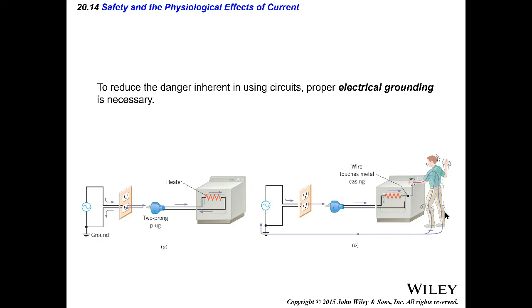That is for your safety, because then you'll be able to say, oh, something is wrong. And then you'll have to see which one is your appliance. You unplug one of the appliances and then turn the fuse box back on to see if something happens.